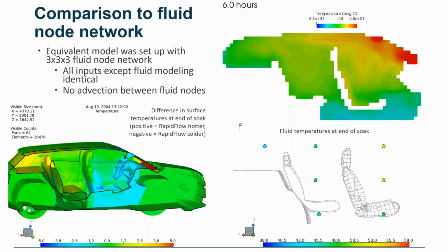And we can see, if you look at the trends and range of temperatures within the area, the bulk nodes are doing a reasonable job of representing the appropriate bulk temperatures associated with those different regions, but they're certainly not capturing some of the local min and max temperatures within each region or across the cabin.